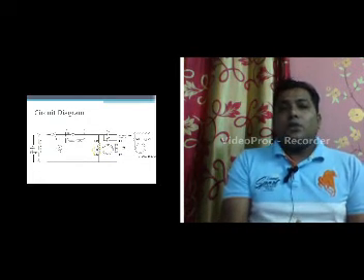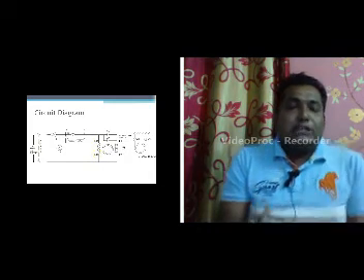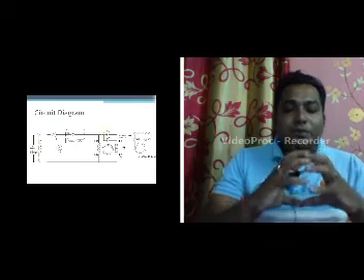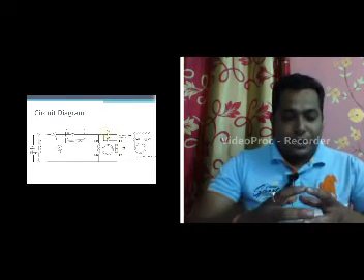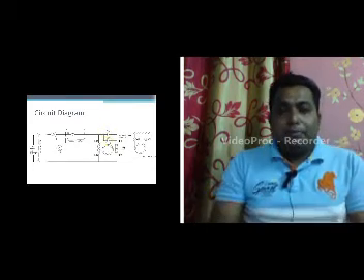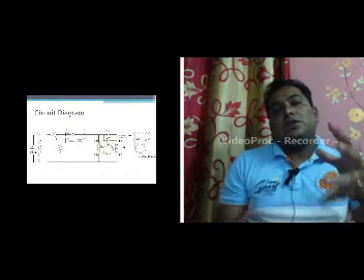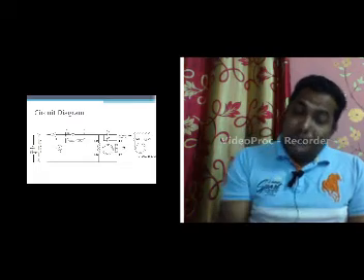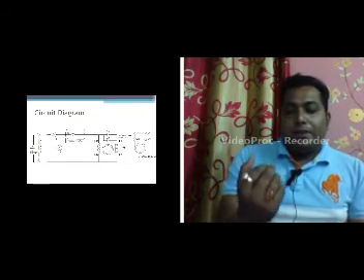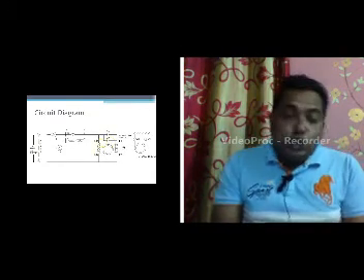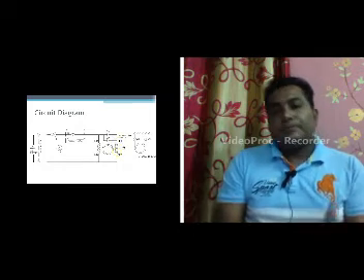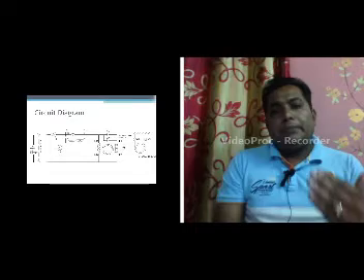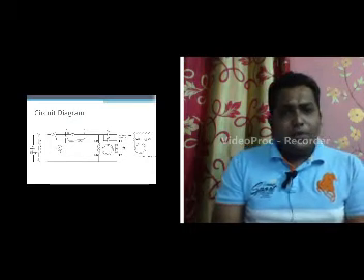So what we will do, the motor is facing some force. We are giving some force so that it cannot rotate. But the inherent property of any machine is that it will remain at its constant speed. So what it will do, it will consume more current from the source, so that it can maintain its constant speed.